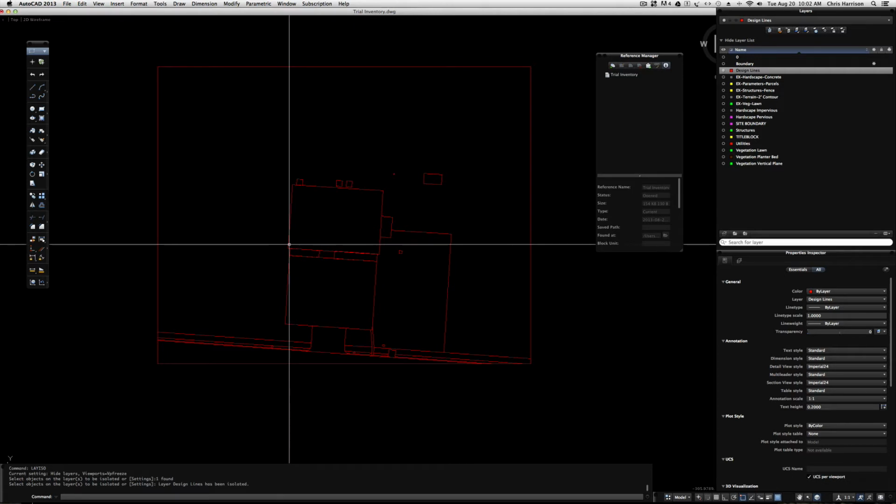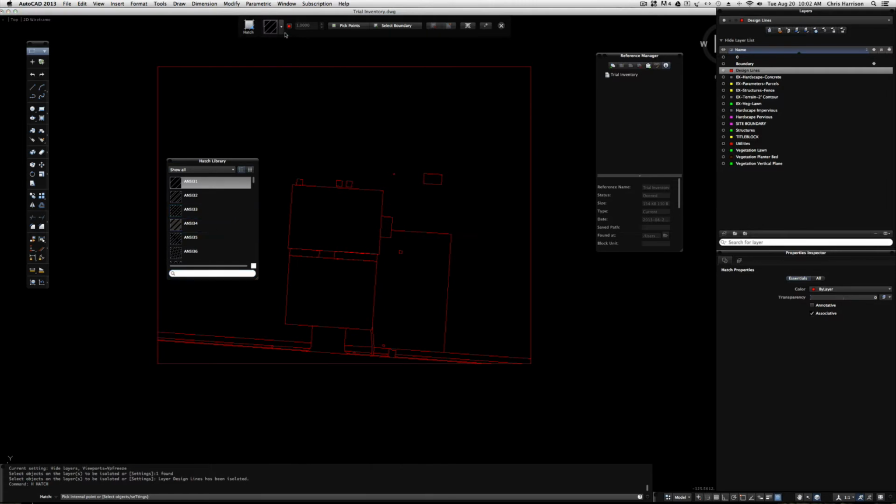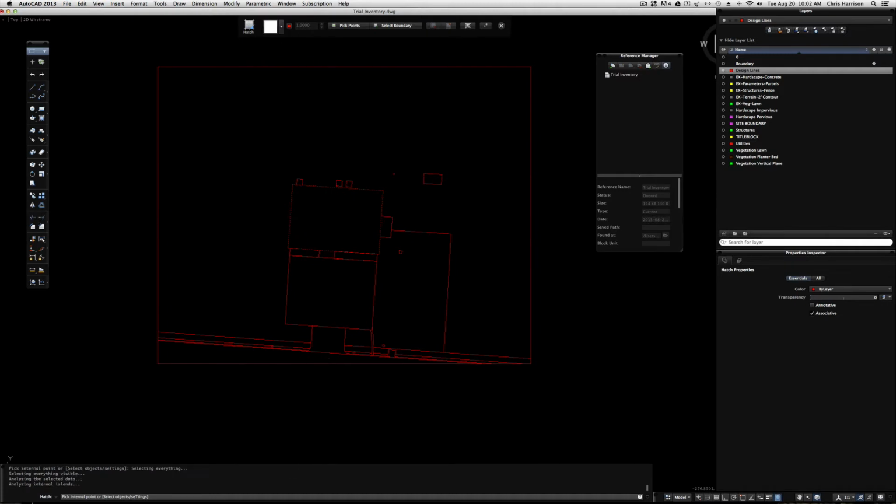So what I did, I just went in, selected my hatch tool, H, enter, select your hatches. I'm actually doing a solid color. Didn't need to be, but just solid color. Made it easier for Photoshop to read it too. Because this is going to serve two purposes. It's going to allow me to calculate the square footage of each piece, and also it gives me a graphic in Photoshop that I can easily manipulate.